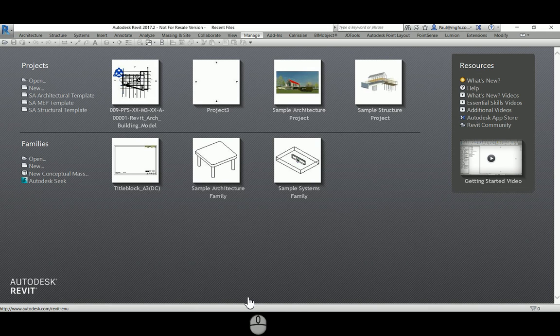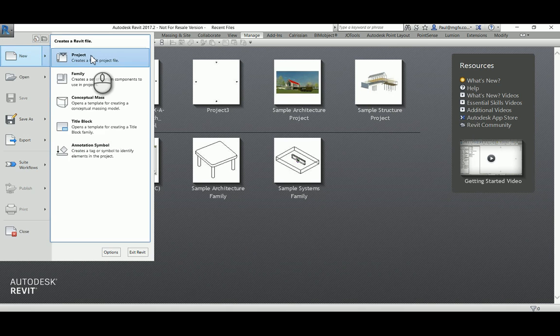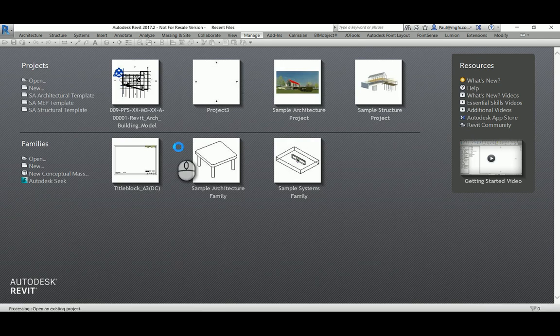And remember, Revit has a project internal point, which is in addition to the project origin and the global origin. Those are the three UCSs. The one you can't change at all. It's always just at the 000 point of Revit. It's a project internal point. You don't see it. It's not annotated in any way. I'm going to create a new project from our South African architectural template.